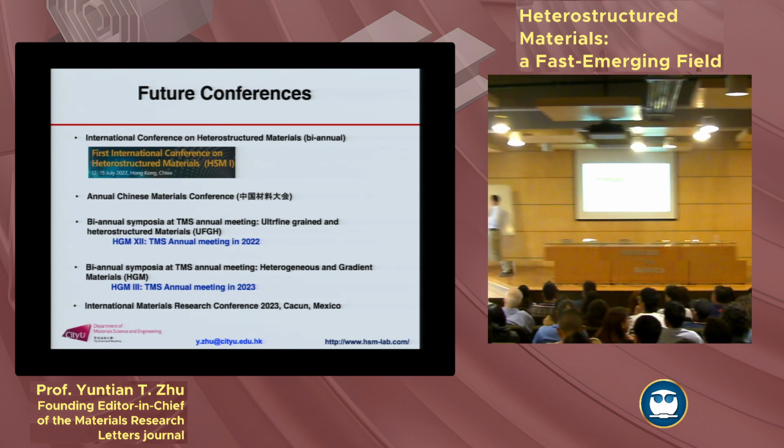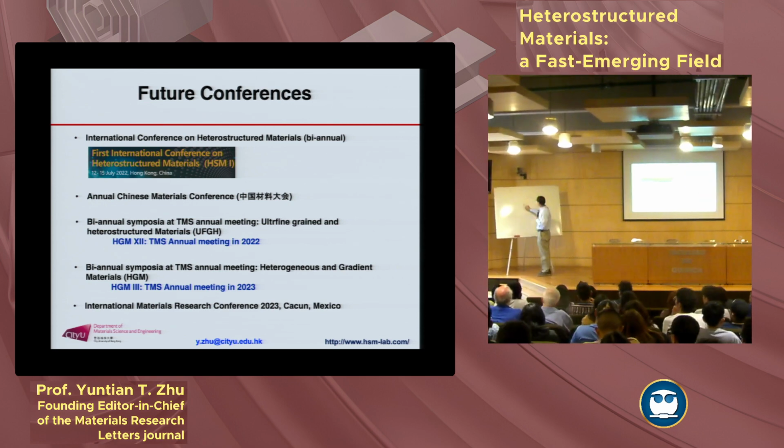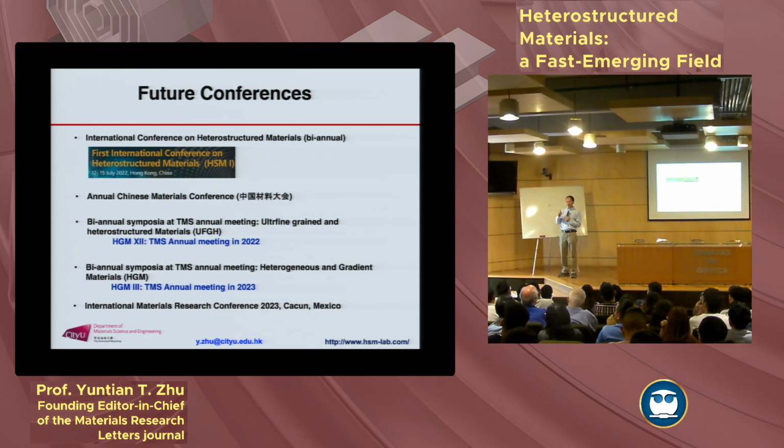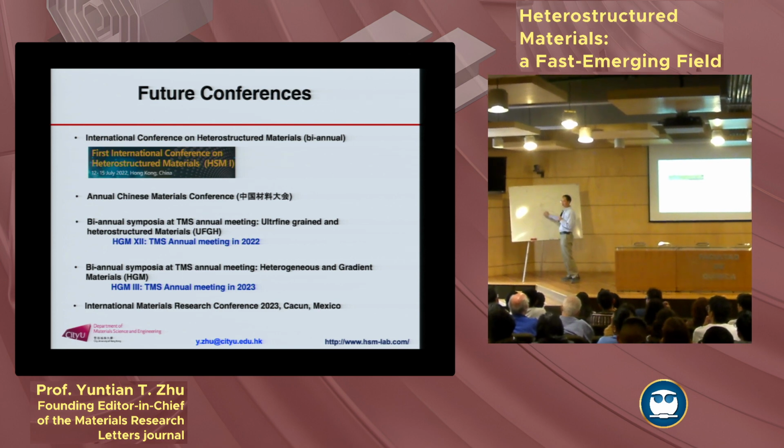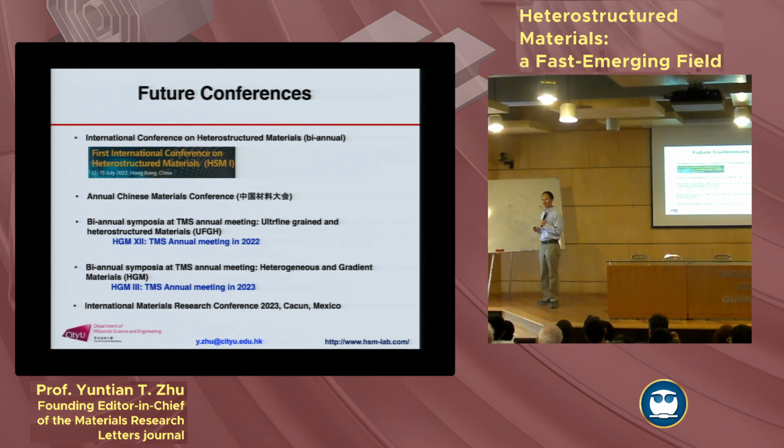Okay, you have a coarse grain, right? You know, each grain has a different orientation. When you do the deformation in rolling, because of their different orientation, their plastic strain will be different, right? So some grains will store more dislocations, some less.